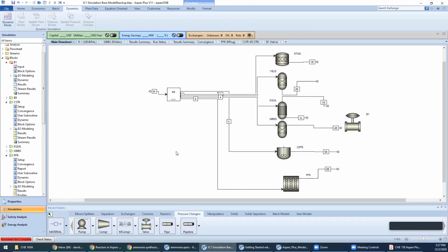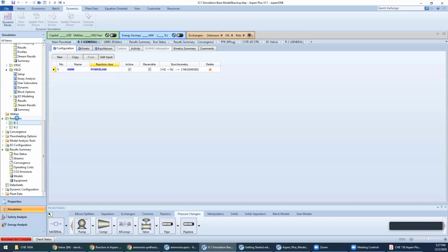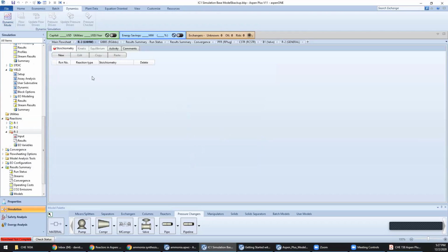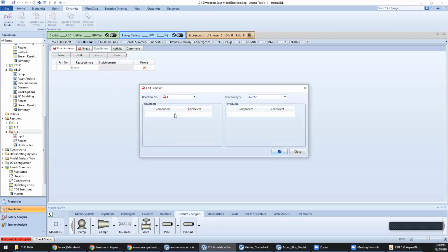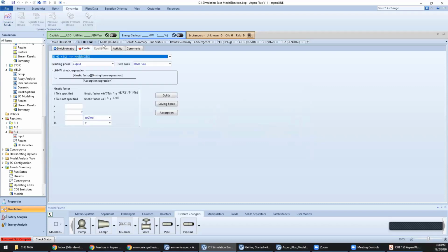And for anybody that's curious, adsorption and desorption kinetics can be taken care of within Aspen using Langmuir-Hinshelwood-Hougen-Watson kinetics. If that didn't make sense, it's cool. But if you click a new reactor type, you go LHHW, so Langmuir-Hinshelwood. Oh man, okay. Let me just make up something. Oh, they did learn Langmuir-Hinshelwood, so. Okay. Yeah, so with that, you have this here.